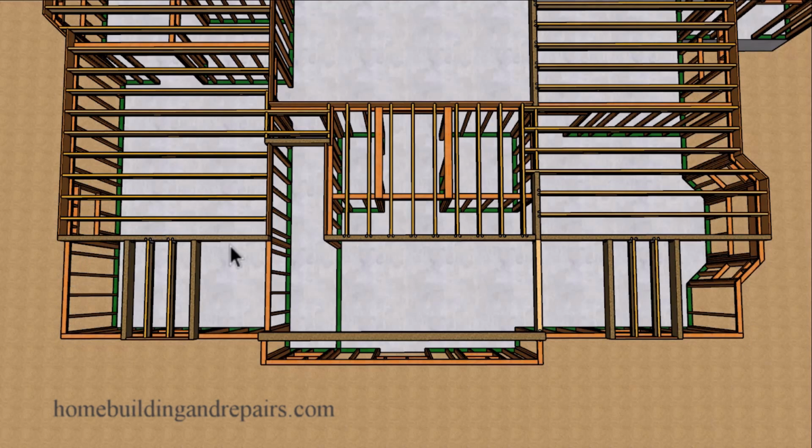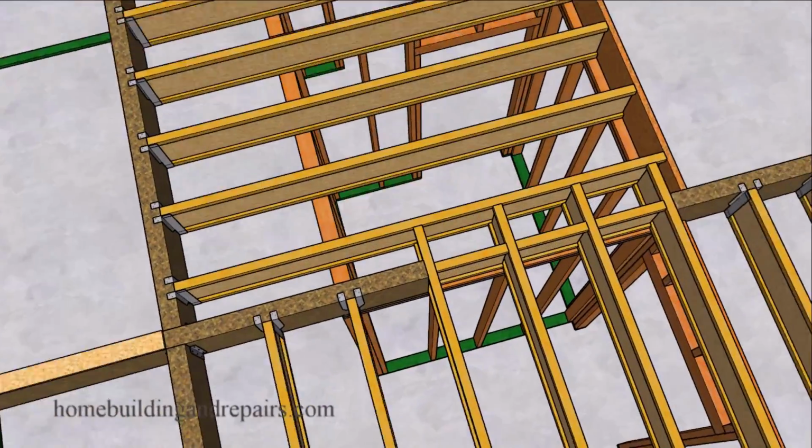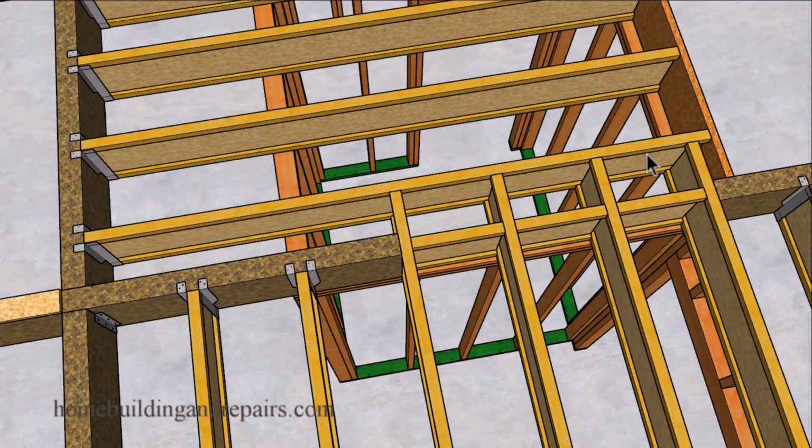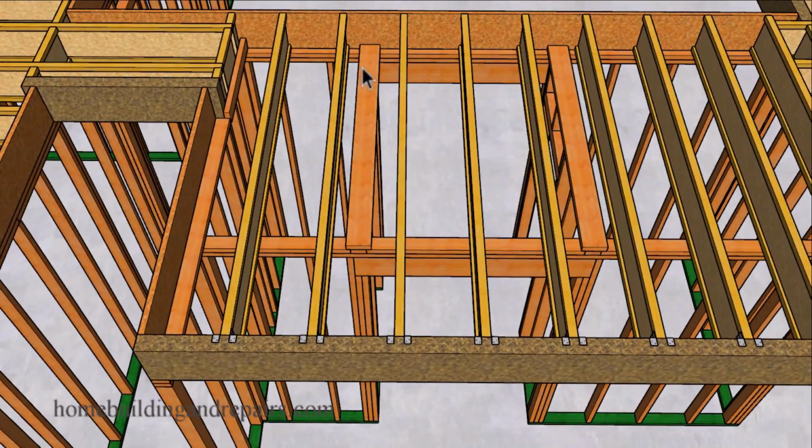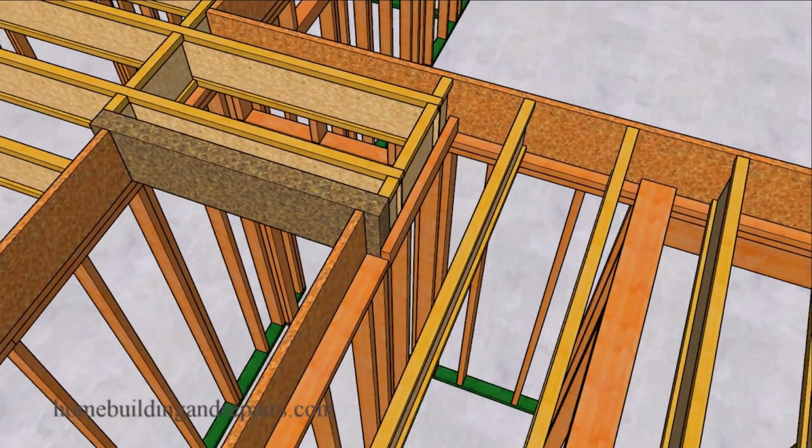Even though that is not going to be the case right here, our stairway is going to create a problem for a connection that's going to run all the way through. And of course that might require additional structural reinforcement. So again, the joist changing directions. And if you have extra lumber, you can butt the joist up against the other joist or stop it at the end of the wall. And of course, our ceiling backing again, we can use a 2x6 instead of two 2x4s here, if of course that will work for you.